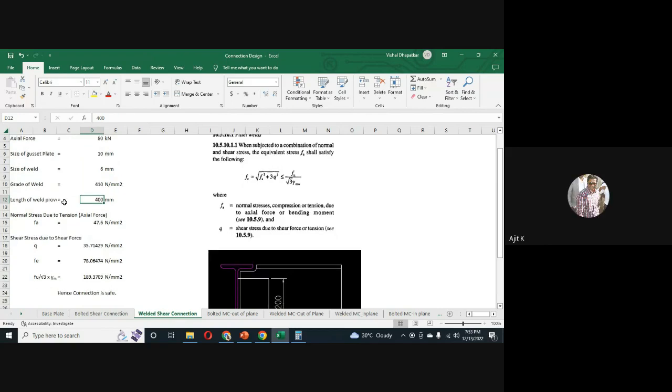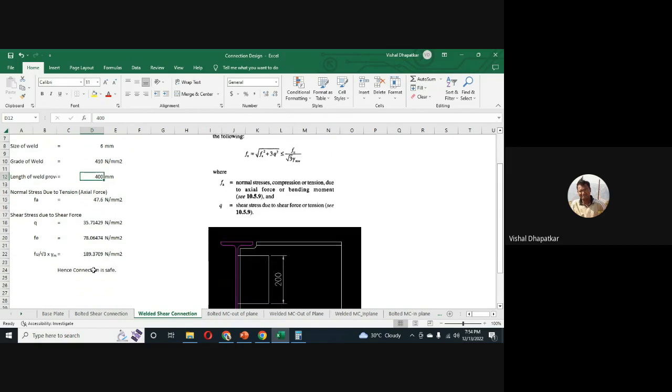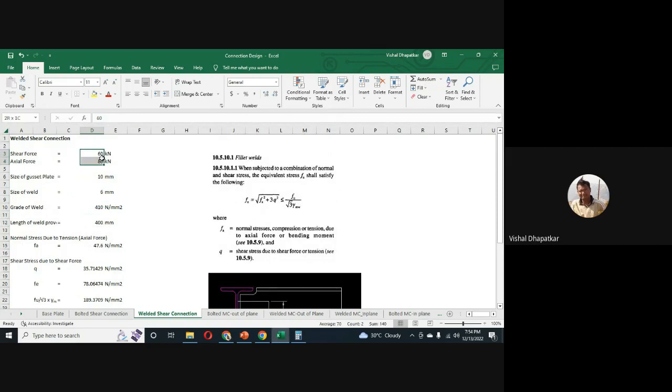ओके, तो अभी इन करंट सिनेरियो कौन सी मेथड यूज होनी चाहिए? Nowadays we are using limit state method only, because our IS 800:2007 is based on that method only. The working stress or allowable stress methods are now not used by anyone. ओके, all combinations or all loads whatever we are considering, those are for the strength combination, like factored combination, not for the service combination. All loads are for the factored combinations. यस यस.